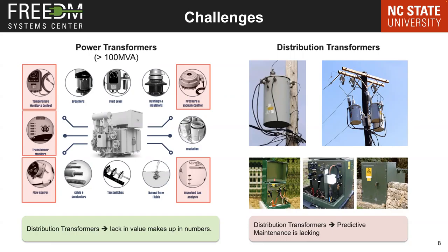So what you've done is a way to use data that you're already collecting versus the expense of adding additional sensors to these lower rated transformers in the distribution system, right? Exactly. For instance, if you want to look at harmonics, you need much more granular data. You might want to revert to micro PMUs, but you cannot install micro PMUs on all these devices. They only install at selected places. So they require different types of data, different sensors. We don't look at those here.